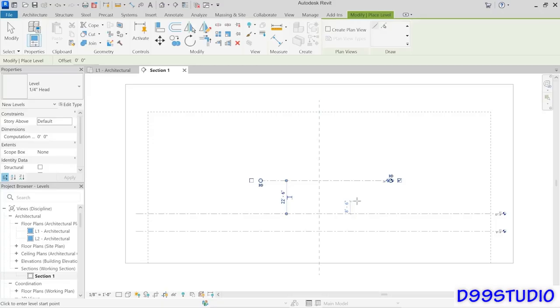So let's create a second level. And what I want to show you is if you move your mouse nearby one of the endpoints of the existing level, it will sense where it is. You can kind of get this little dashed extension line there. And if you click, that's going to keep those 2 points lined up with each other. And we can do that on both sides. So notice that it kind of senses it over there as well. And it even locks those points together.